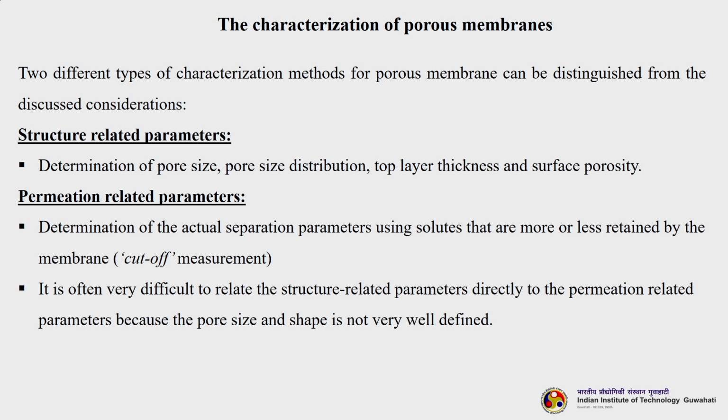Now, when we talk about characterization of a porous membrane, it is actually of two types: structure related parameters and permeation related parameters. Under structure related parameters, we basically determine pore size distribution, top layer thickness and surface porosity. In the case of permeation related parameters, we determine the separation parameter using some real solutes that are more or less retained by the membrane surface. This is called cutoff measurement or cutoff experiments.